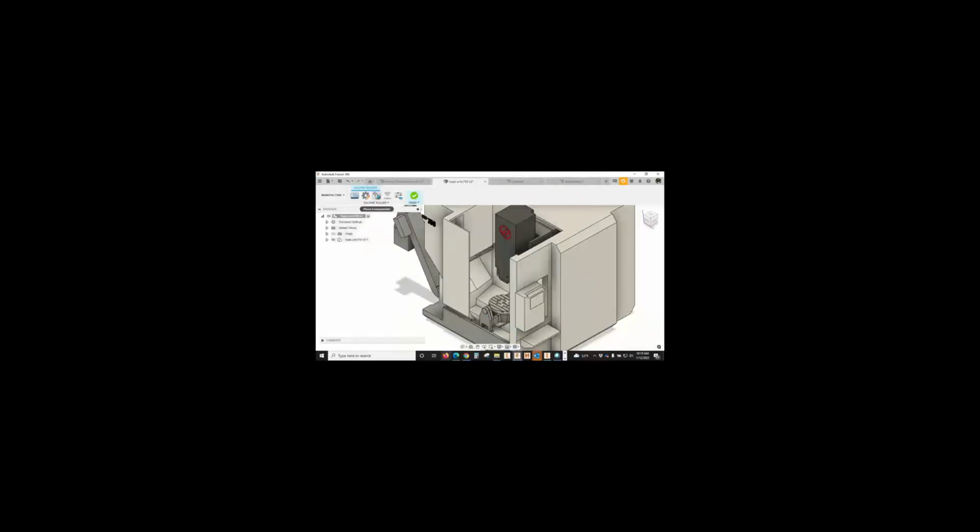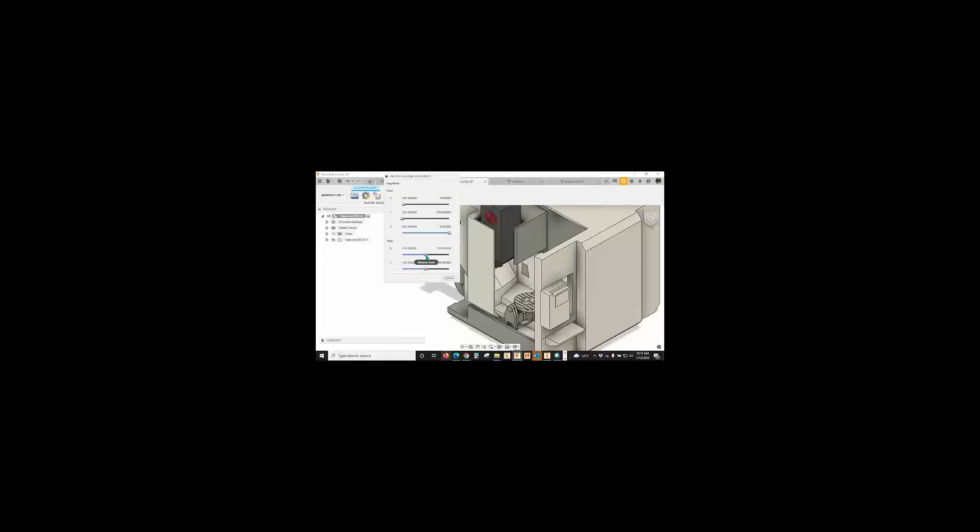And so on each rotary axis, I can come in and either change the coordinate, maybe it's an A axis, give it a home position, max feed rates. And I can also come down here and, for instance, this B axis, I can change the range of it. Okay, so right here I have a minus 110 to 110 degrees, and then that's where I can come over here to my movements, and I can actually see what that's going to look like. So on this B axis, you'll notice I can get a good manual view of the range I put in. So we can test out these limits after we make our edits to the machine.